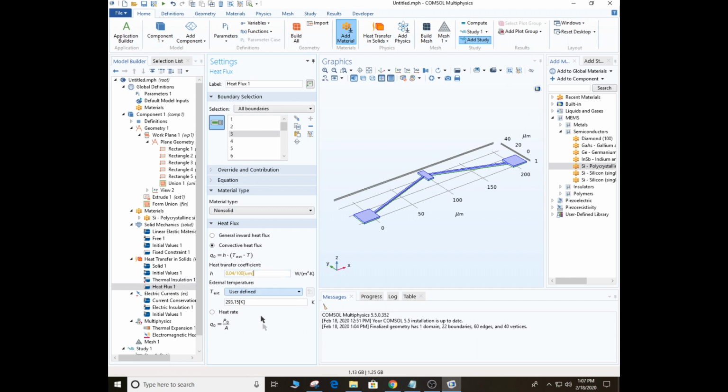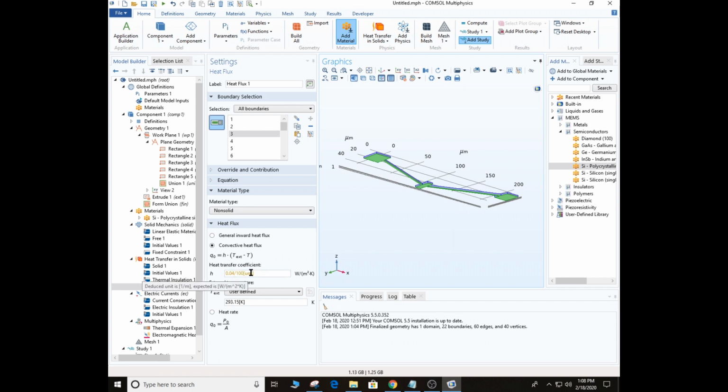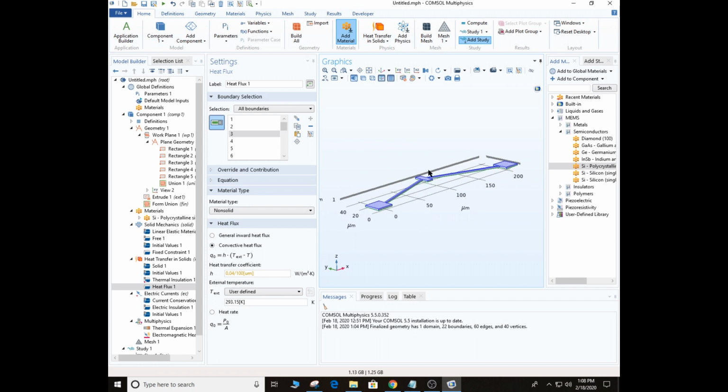Remember how it was done last time, where this dimension right here was, you know, what size. Before, the surfaces that were close to the substrate, we made 2 divided by 2 microns, and the top surface, since that was more exposed to the ambient atmosphere, we made 100 microns. And so here we're being a little lazy and just saying it's 100 microns everywhere, which should be fine.